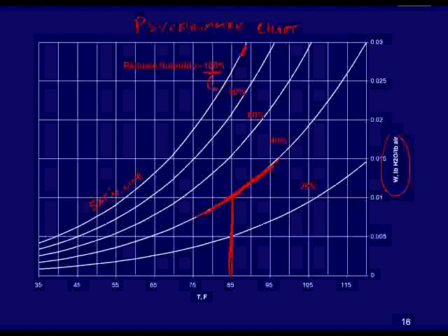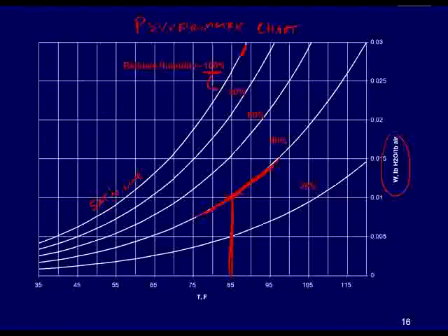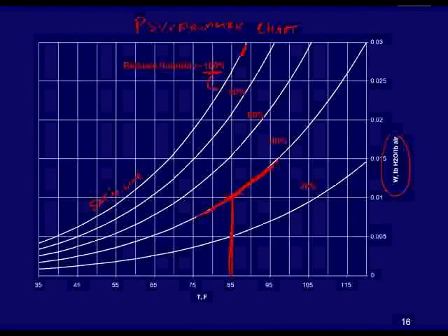Now you recall the dew point is the temperature at which we cool. Now if you cool the air-water mixture, you're going to lower temperatures. Cooling is in this direction. If we cool that air, then the absolute humidity doesn't change. There's still that water in the air until you get it saturated. Once you get it saturated, now you'll be able to form droplets that will take the water out of the air and cool it along the saturation line.